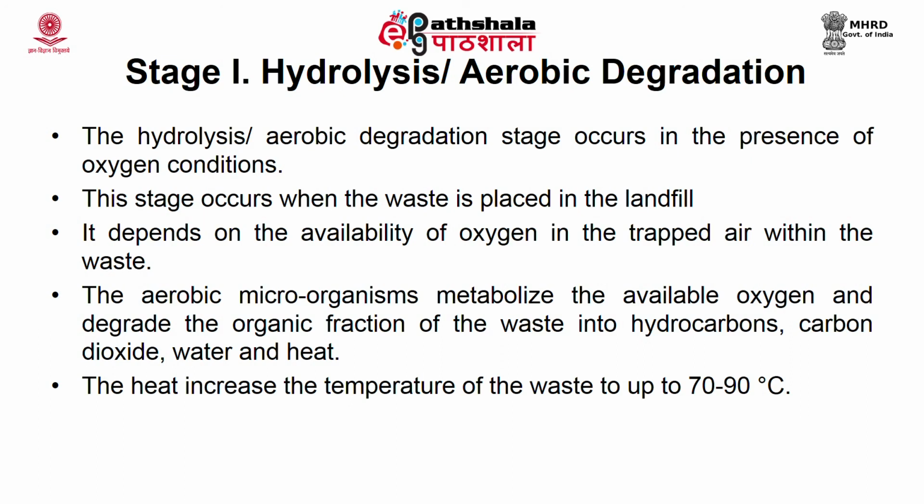Now, these complex organic compounds are broken down by aerobic microorganisms, or hydrolyzed into simpler substances. Now, oxygen plays an important role in stage 1, that is hydrolysis or aerobic degradation. This step occurs during the initial few days of waste emplacement within the waste landfill.